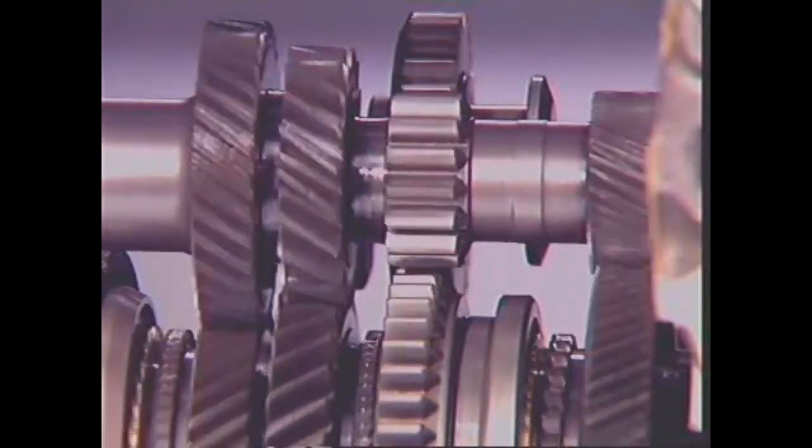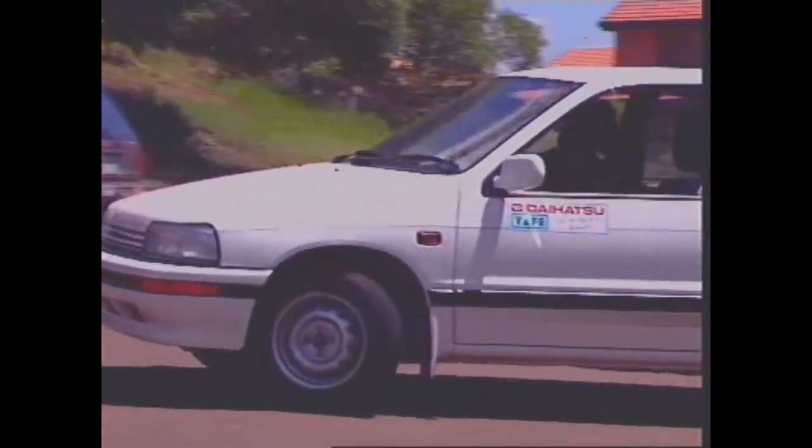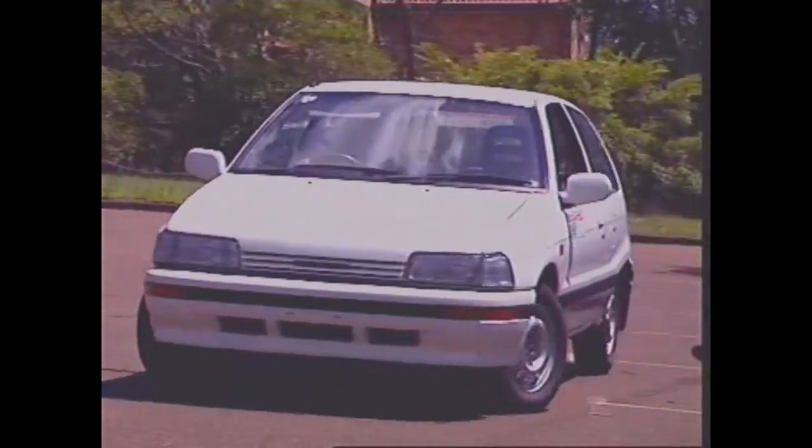Drive transfers through the idler to the splined secondary shaft sleeve. The idler between the shafts makes the secondary shaft rotate in the reverse direction. This reverses the direction of the final drive ring gear and the road wheels.